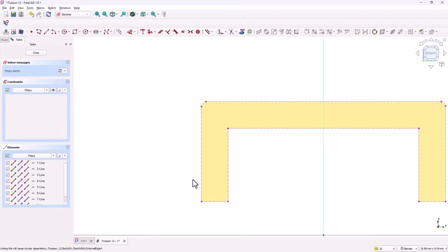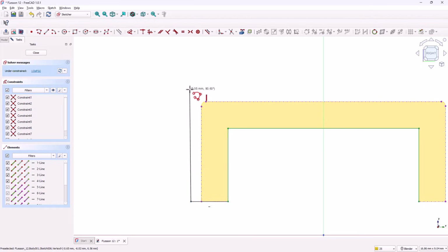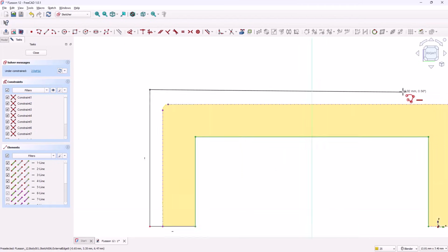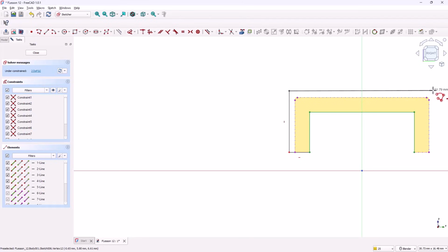Once the references are in place, grab the polyline tool and start tracing the inner profile of the shape. For the outer edges, make sure to extend slightly beyond the reference sketch. This is intentional because the strip should extend just a little past the surface of the knob for better visibility. Continue sketching the full profile, and finally, close the profile by connecting the last point to the starting point.